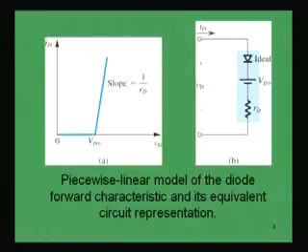So, this whole part will be the diode's representation, and in an electrical circuit we denote it by this model. So, this is VD0, that is 0.7 volt around for silicon, and this average resistance, of course, we have to find out given two operating points, and this ideal diode is just to symbolize the direction of conduction of this diode. So, this model we have found will be representing the characteristic of the diode, of course, in the piecewise linear approximation.